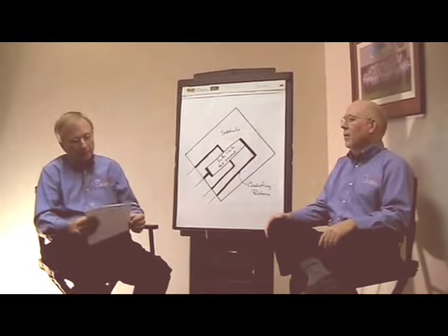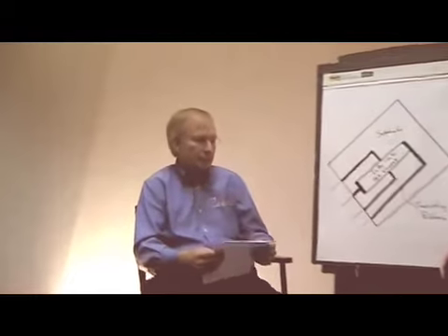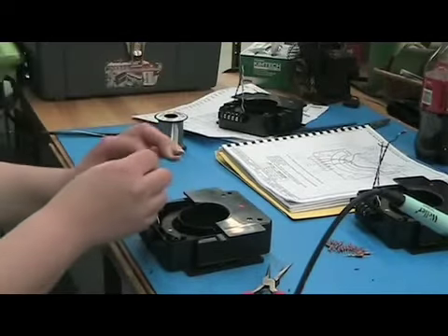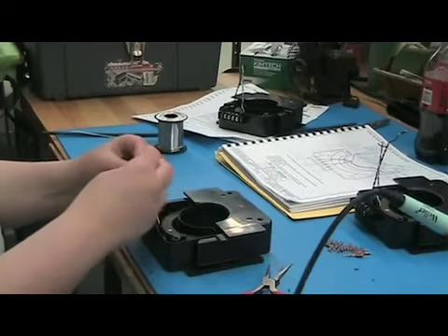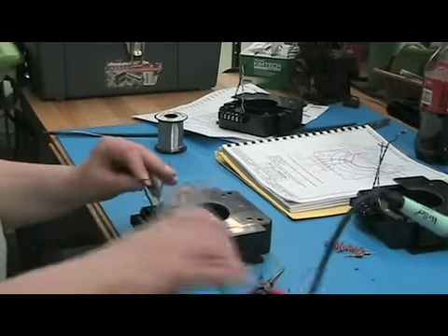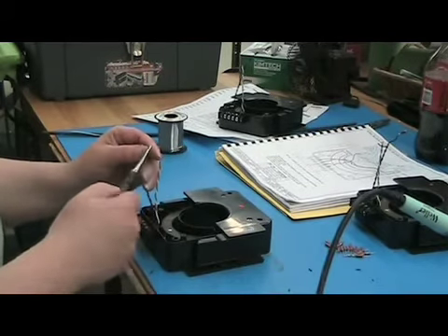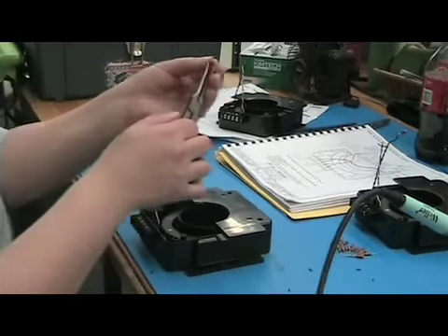Great question. I think the answer lies in the fact that the Hall effect can do DC measurement as well as AC measurement. Many of the techniques will only do AC and not DC, but the Hall effect will do both. So anytime you need both AC and DC, Hall effect is a good choice. And as we mentioned earlier, there's the non-contact safety that you gain from not having to make a direct contact to the power distribution system that you're measuring on, resulting in no shock hazard.